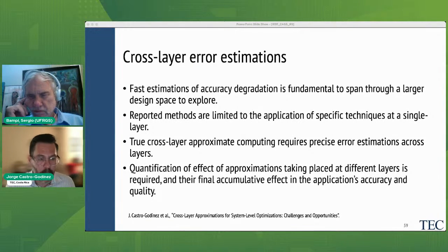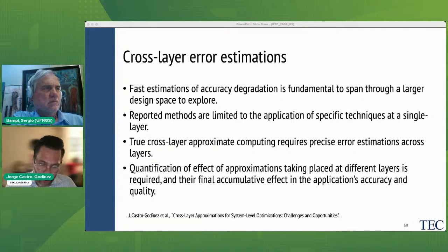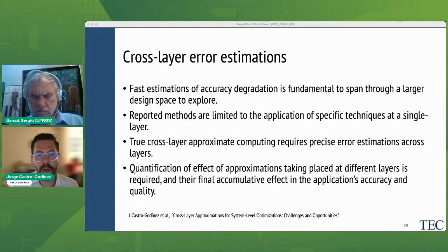But this is the way, at least in the works that we have been contributing to the community from this perspective, exploiting a standard high-level synthesis tool, which we're using. It's Vivado HLS so far, moving also to Vitis HLS. It's basically that. Find what is going to be the Pareto optimal solution for the accurate implementation, and from that point onwards, introduce the approximations as much as we can to then explore the design space.